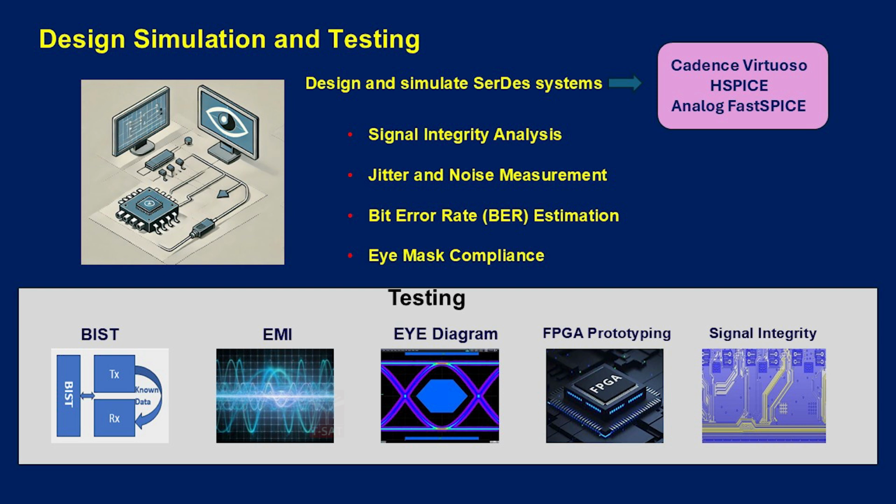Let me try to give you some understanding in terms of packaging. When we have the device in a PCB or somewhere, it is encapsulated in a package. It's not a bare die. The die has signal pads, which we call bumps. The signal bumps and the power bumps are connected to the package bump.